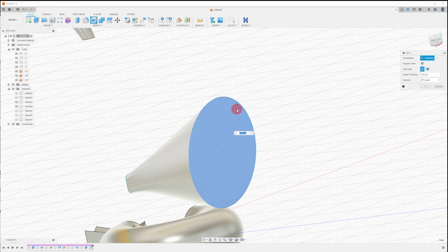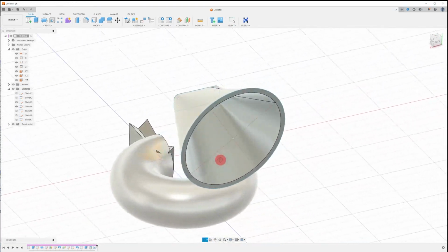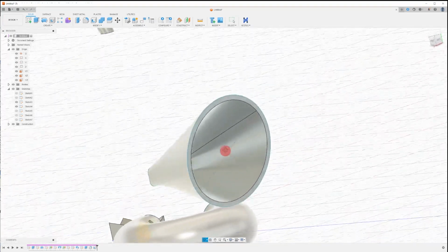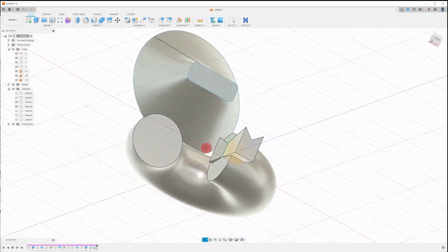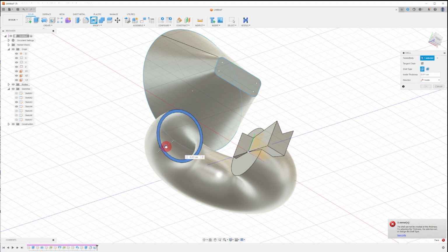With this selected, I'm going to drag this arrow, and when we see it compute and hit OK, we're going to see that it has now shelled out, it has hollowed out this shape. We can do it here on our toroid, our donut, if we click on shell and click on this face, and we can drag that arrow and hollow it out with a thickness, and this value is the thickness of the wall, and hit OK.